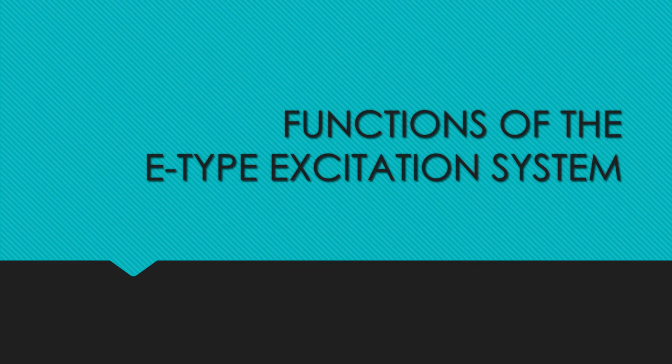Hence, the excitation system must also impose electrical limits on the main generator, that is, maximum voltage and current, to avoid the possibility of damage to the insulation by high voltage or excessive current. In the locomotive, the load on the main generator at any fixed engine speed varies as locomotive track speed increases due to counter EMF generated by the rotating armature of the traction motors. Therefore, the excitation controls must keep the alternator HP demand constant over a wide range of terminal voltage.